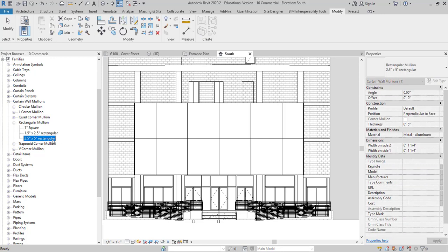I'm going to right click. I'm going to choose duplicate. It's going to make a brand new one, and I'm going to call this one spandrel. So this is going to span over the floor thickness. So I can open that up now. If I select that, I can see what spandrel is, and I'm going to make a few changes. All these changes are discussed here in the book, and I'm not going to go into all these details, but you should take a moment to read that.